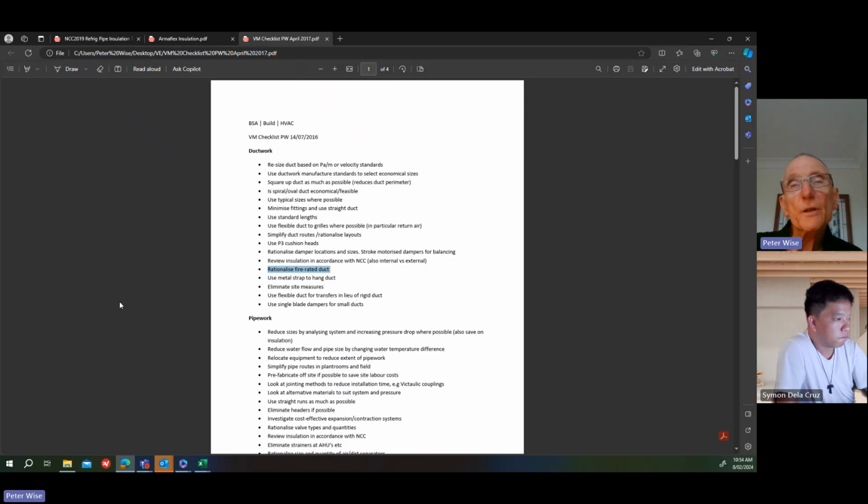And basically another example is if you have a fire pump room. Okay, a fire pump room has to be a fire rated compartment, because in the pump room you have the pumps that pressurize the hydrant systems for firefighting. So if there's a fire, that room has to be separated from the building so that those pumps can continue to run. You don't want that part of the building to get on fire and the pumps fail and they've got no water. The fire brigade has to have constant supply of water so they can fight the fire.